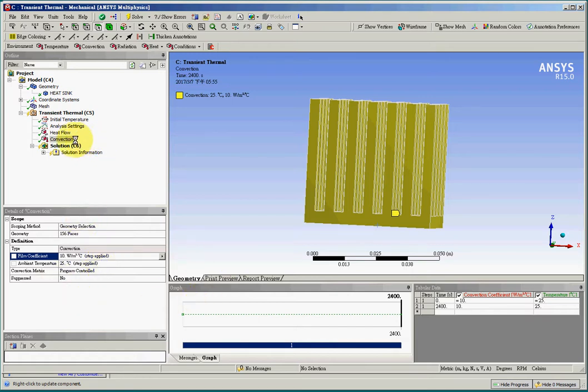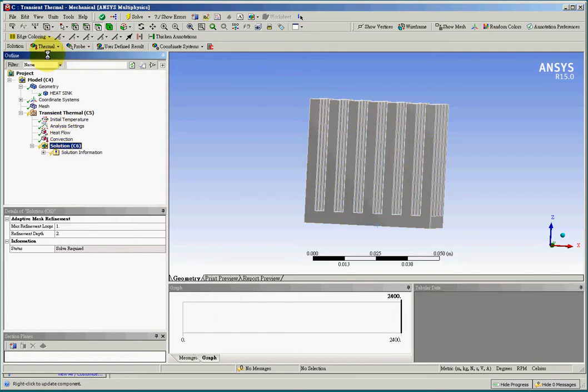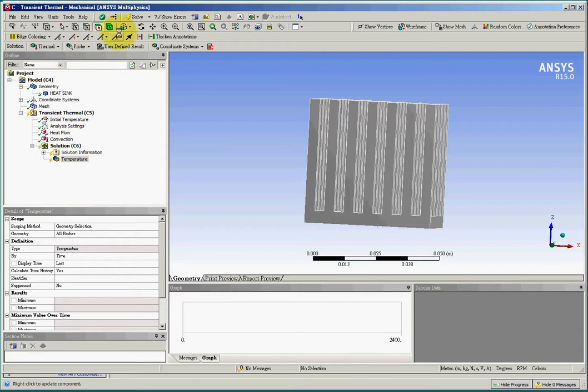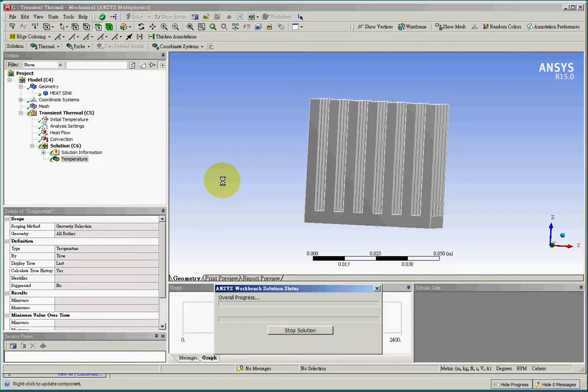And this is also very important, that the convection coefficient of stagnant air is 10. So this is a convection coefficient for still air. The air does not move, a stagnant air. So now I can go ahead and implement the solution. So I can choose the result to be temperature result and calculate. And this is step 5. For step 6, this is the result.